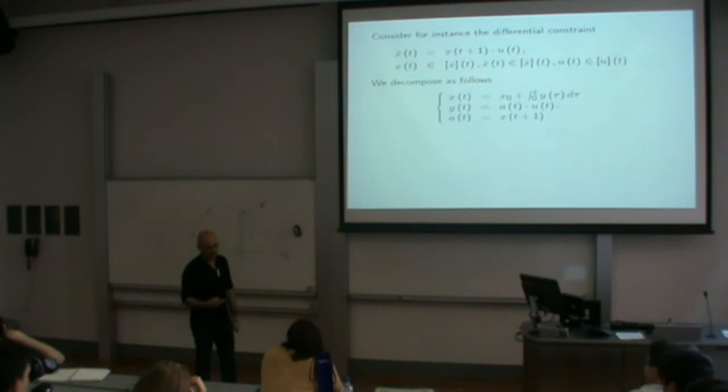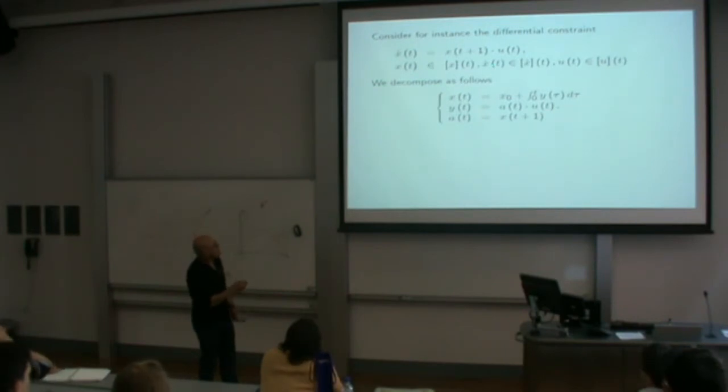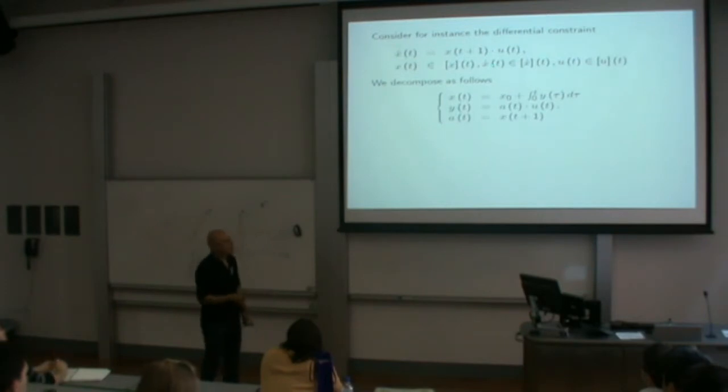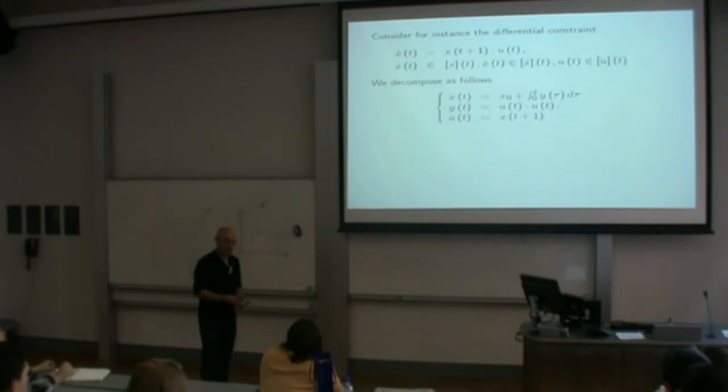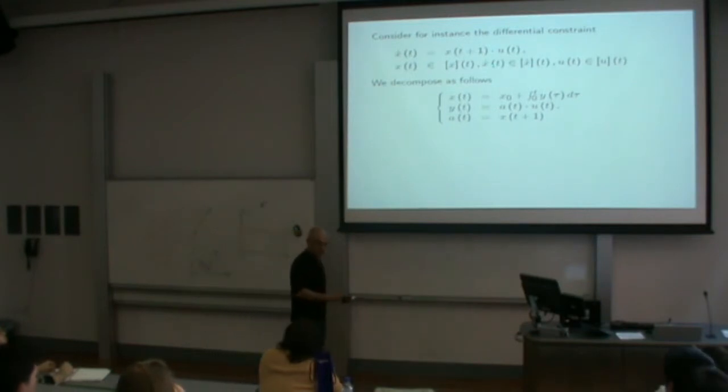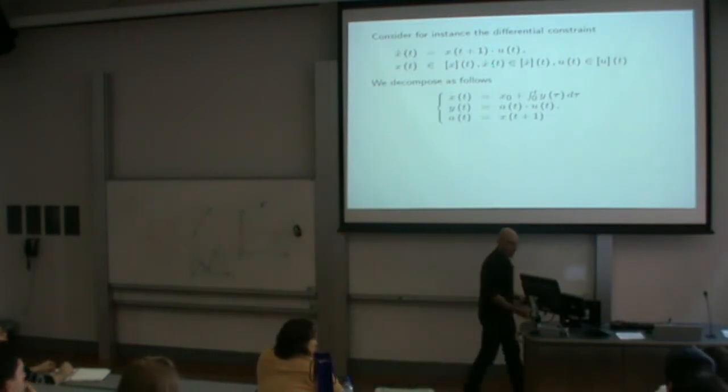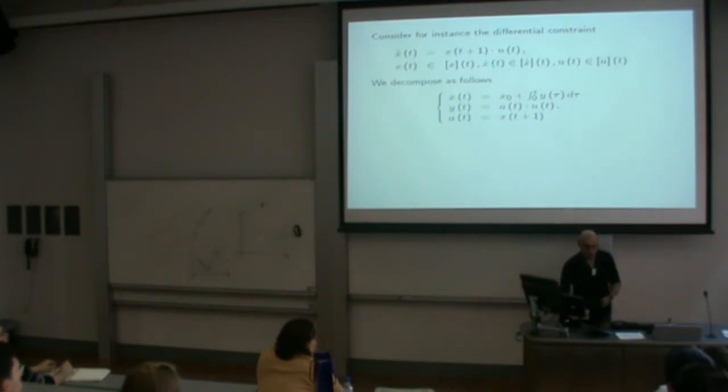I can say that for our problem, with submarine robots, we are not able to measure X. So this one, most of the time, is minus infinity, plus infinity, except when we are at the surface. But the velocity, we are able to measure it. And that is a big difference. And why are we able to measure it with a good precision? Because we have a Doppler log, which means because of the Doppler, you are able to know the velocity of your submarine. Okay?